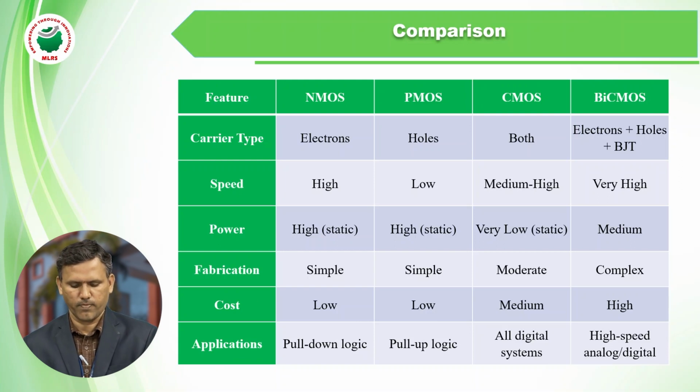Power consumption: high static in NMOS, PMOS also high, CMOS very low static, in BiCMOS medium. Fabrication: simple fabrication for NMOS and PMOS, moderate in CMOS, complex in BiCMOS.